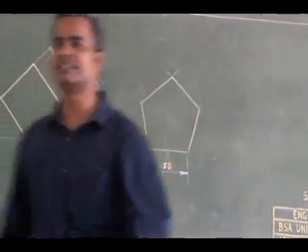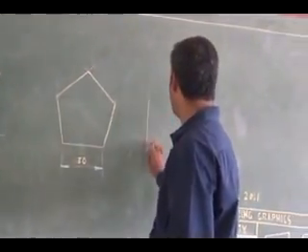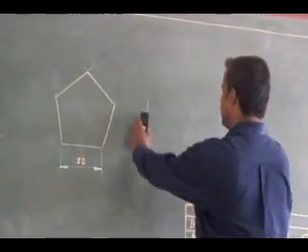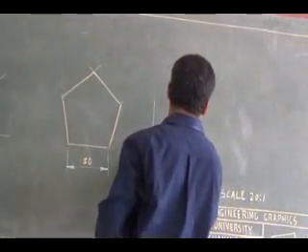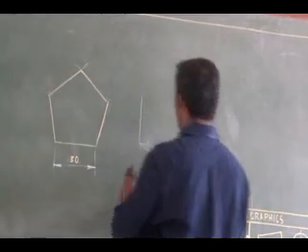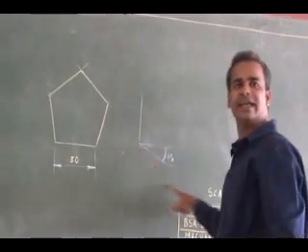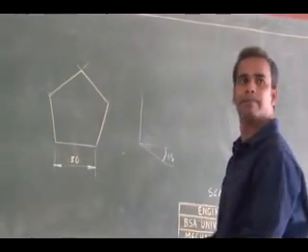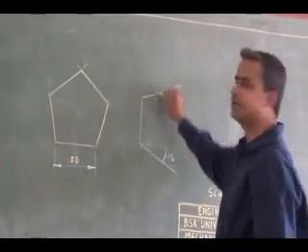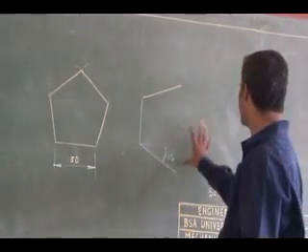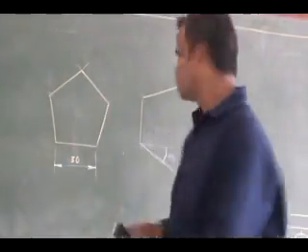Right. How can I construct the vertical pentagon? I can draw a vertical line like this, 30 mm. Then my drafter will be like this now. Using the drafter scale, I can move it here so that I can get the inclined side. This side I can get by tilting my drafter 18 degrees, and this side by tilting my drafter another 18 degrees. Then from here I can draw two arcs and construct a pentagon. This you can do now.